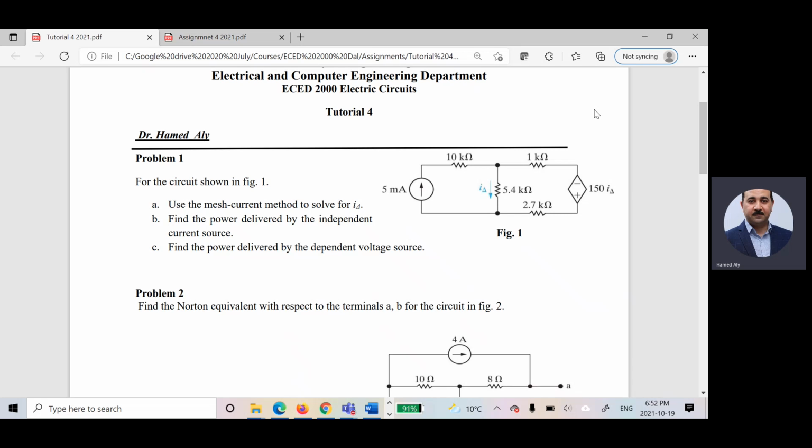You have to find the Thevenin equivalent first, and then you will say for maximum power transfer through that resistor, the variable resistor should be equal to R Thevenin. Number three, if I give you a resistor with different values, and I ask you to solve the problem many times based on different values for the resistor to calculate the current or the voltage for that resistor. At that time, it's better to find the Thevenin equivalent, right?